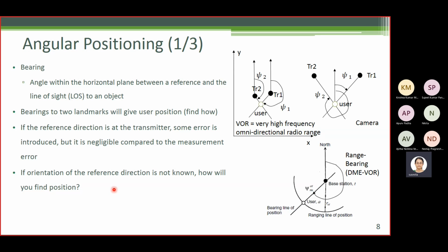Assume that there is no error. In the equations, you make perfect measurements of the bearings and then solve the equations to find the xy coordinates and the unknown angle of the reference direction with the y-axis.